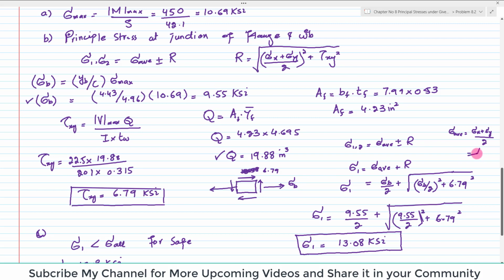Sigma average will become equal to sigma B over 2. Clear? So sigma 1 is equal to sigma average plus the square root of sigma average squared plus tau xy squared. Sigma average is sigma B over 2 and tau xy is 6.79. So if you calculate it, you will get the principal stress at the junction, which is 13.08.